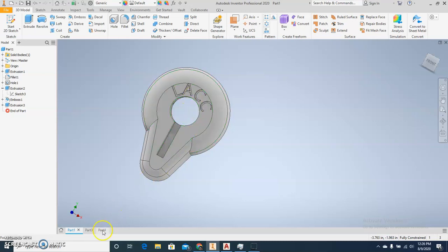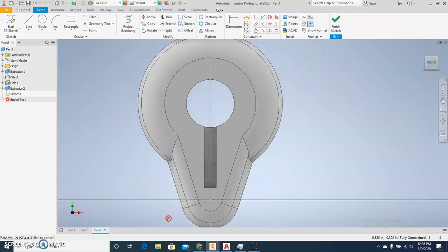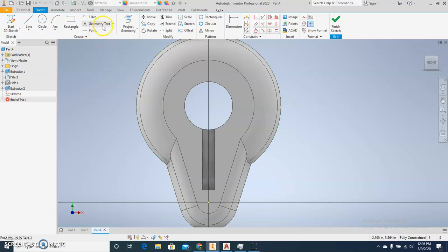Okay, so we're going to play around with it for a minute. So, first thing we're going to do is we have to create some geometry. So circle. Now, I'm trying to find the center point of this. So, if you move your mouse around and touch these circles, don't click, just touch, you'll see how it'll snap on. I'm going to go 1.4 and then just press enter.